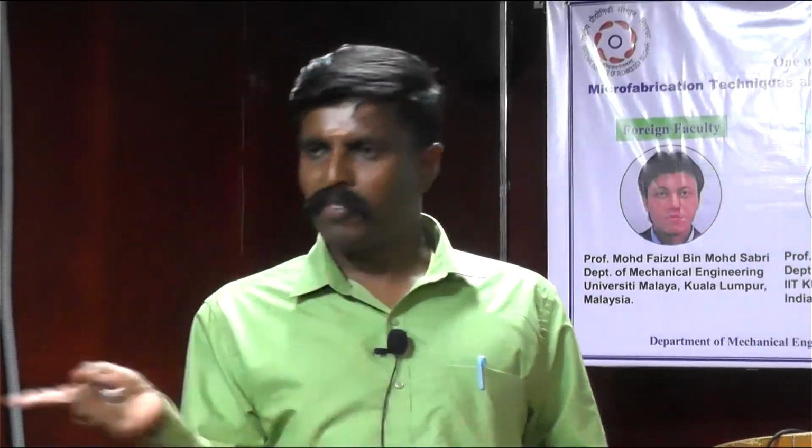The second thing is the material thickness. If it is thinner material, heat conduction will be very fast. If it is thicker material, it will be minimum. So these are all the parameters. Out of these, heat input is the controlling one.